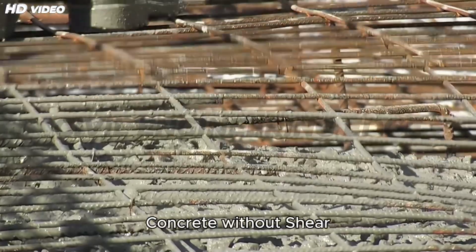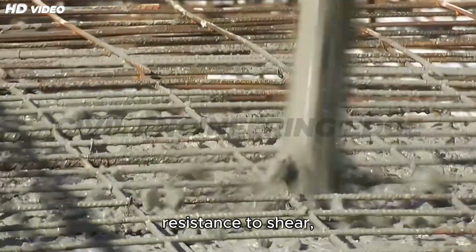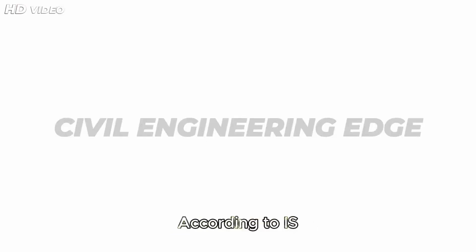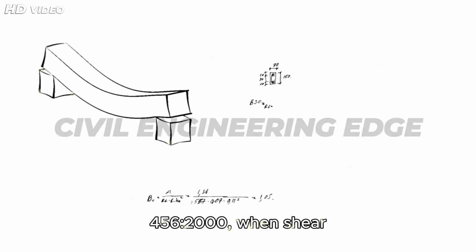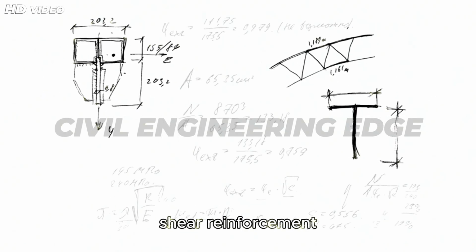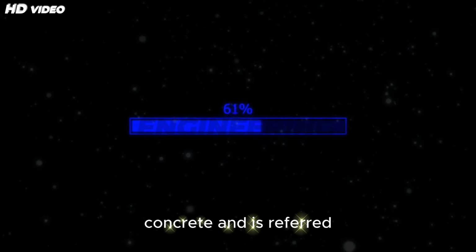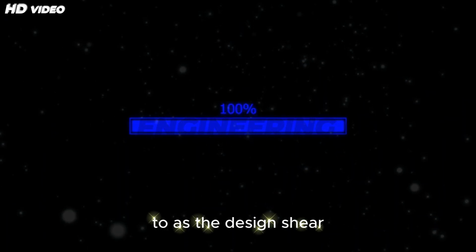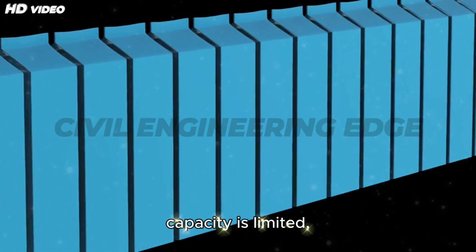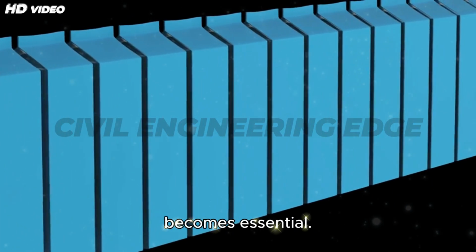Shear resistance of concrete without shear reinforcement. Concrete inherently offers some resistance to shear, primarily due to its compressive strength and aggregate interlock, according to IS 456:2000. When shear stress in a section is within permissible limits, shear reinforcement may not be required. This permissible limit depends on the grade of concrete and is referred to as the design shear strength of concrete, denoted as tau c. However, this capacity is limited, and once shear stress exceeds tau c, shear reinforcement becomes essential.